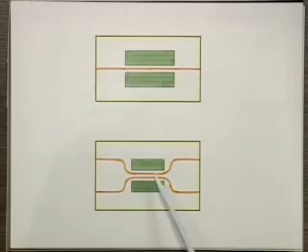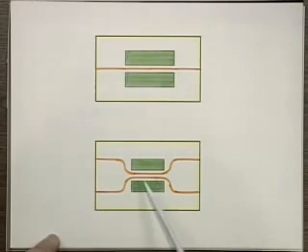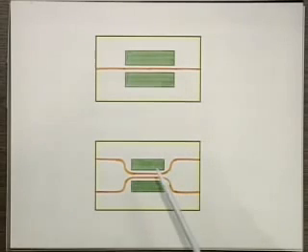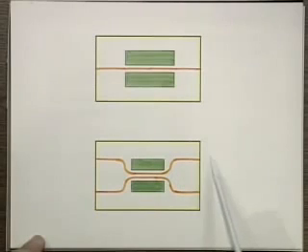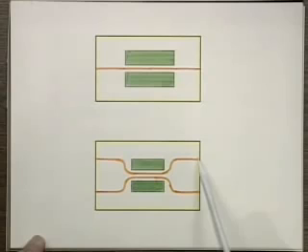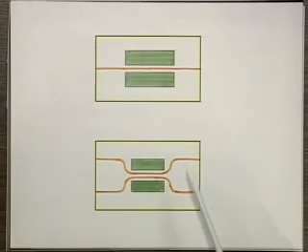You can also use it, for example, as an intensity modulator by applying a variable voltage here, and then you can vary the transfer of light from this port to this port and so on. So it has many applications, sensors and so on. This is a very important field in fiber optics, as long as you know how to couple back into fibers in a rigid way without any reflections or big reflections. So it's a very exciting development.